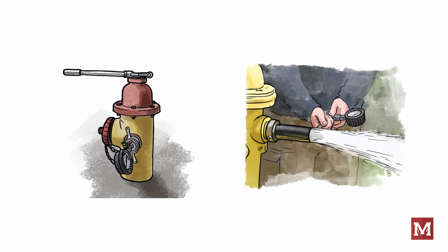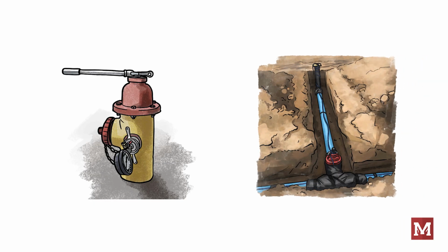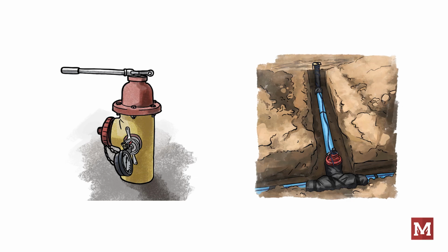And because we need to calculate all the way back to the test hydrant, it's critically important that we have a picture of what that network of underground fire line piping looks like. We need to know the size of underground pipe, what it's made of, the locations of any valves, T's, 45-degree elbows, etc. So having a good civil drawing of the underground is pretty crucial. This is so very important that I generally don't even begin any design work until I have it all together.